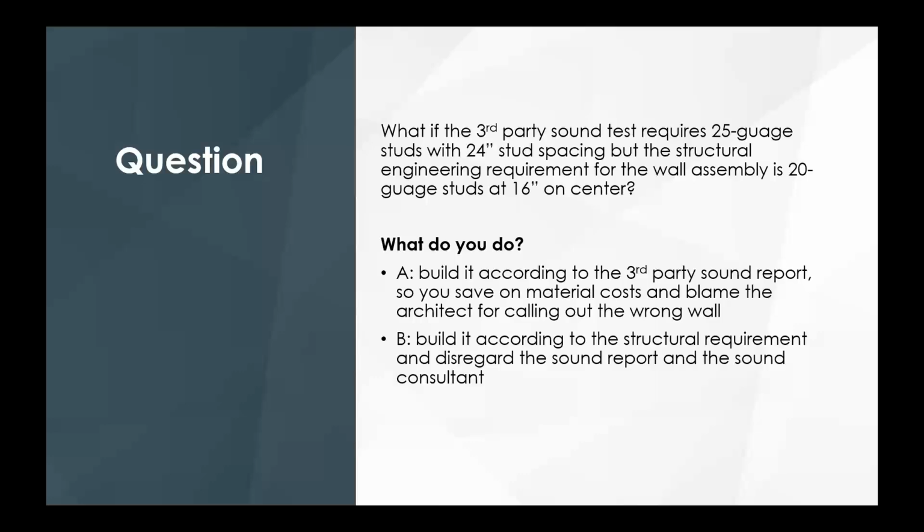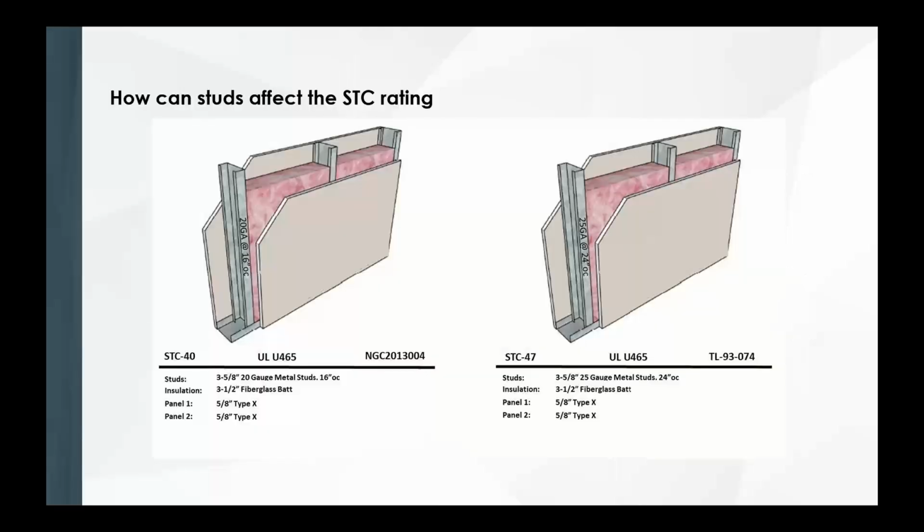Or you say, forget that. I'm going to build it according to the structural engineer, and I'm going to disregard the sound report because, hey, it's got to perform structurally. Or C, inform the architect that there is an issue and ask for guidance. Obviously, the answer is C. You want to get guidance from the architect. This is a true dilemma here. What do you do? Ask them. Going back to that wall again that I showed earlier, STC 40, STC 47,